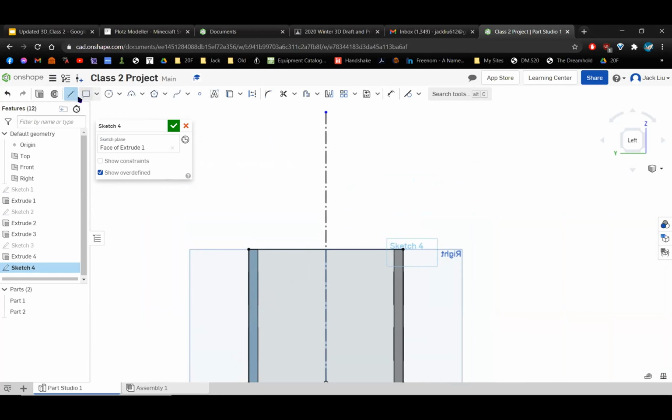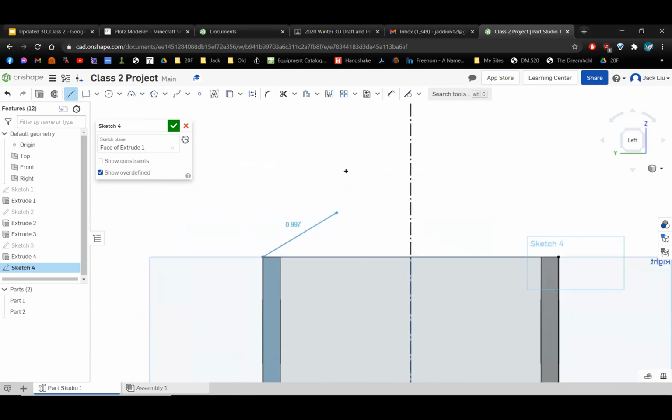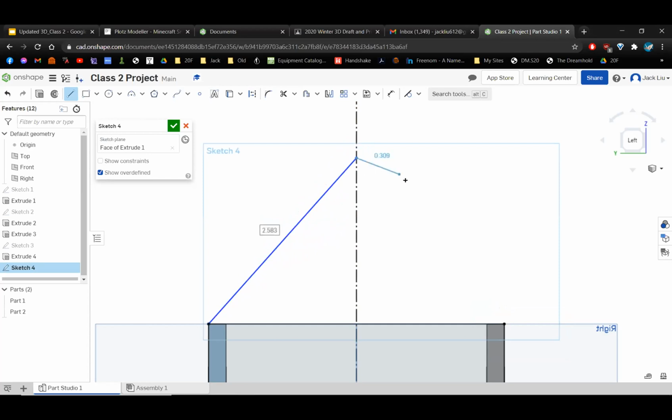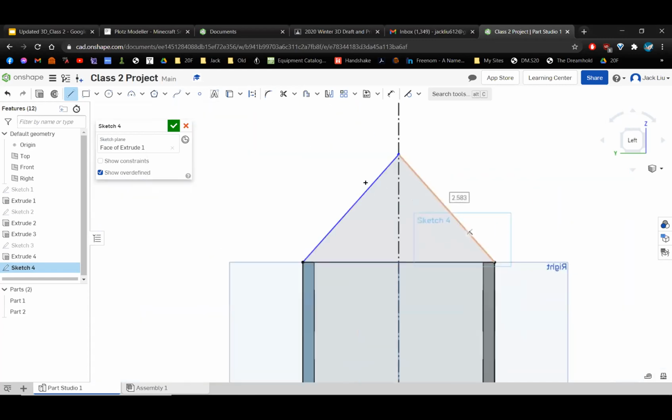And now we want to add that slanted rooftop. So we click the line tool and we use the corners that we created. Make sure you use the outside edge because we don't want the walls to be slightly too small. We want to use the outside corner. Click there. Then I'm going to click somewhere on my line. Doesn't matter right now because we're going to add the dimensions later. So I'm just going to click somewhere on my line. Again, it snaps to it. So that's how you know you're doing it correctly. And it should be highlighted in yellow. You click it there, and then we want to click again on our other corner, our opposite side.